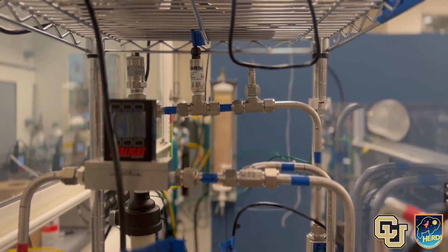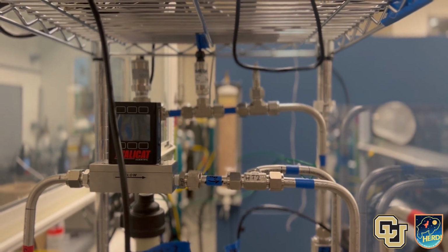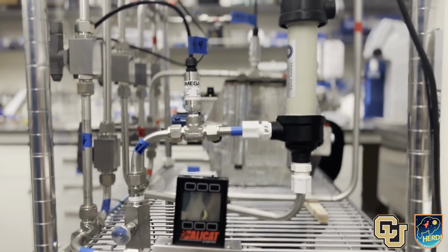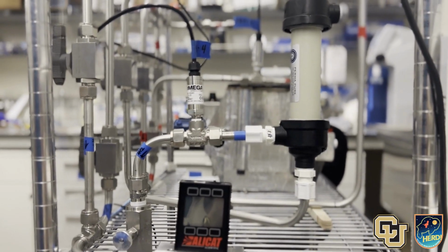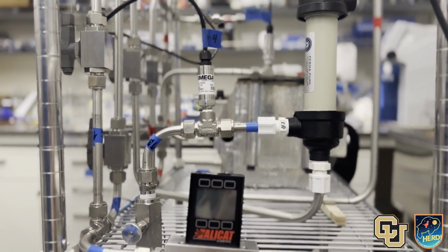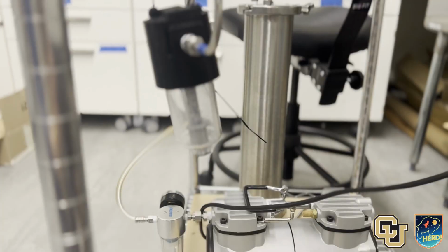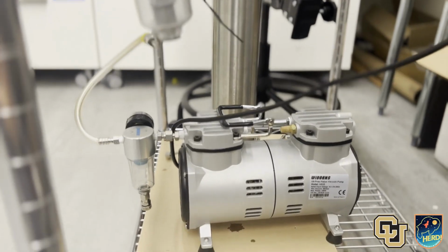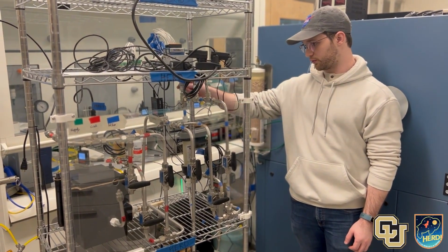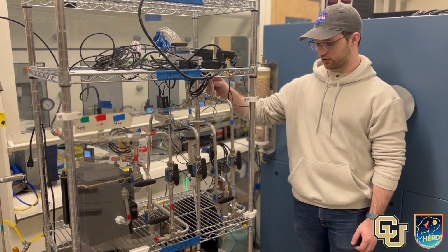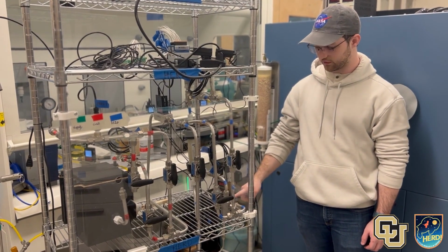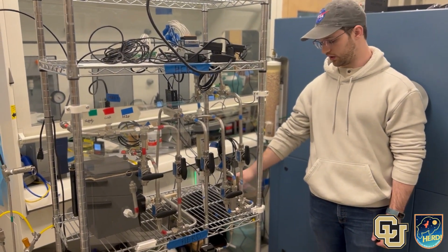And then that air is sent over to the humidity removal subsystem, which is a Nafion bundle, which removes the humidity through a difference in partial pressure of water vapor between the airstream and a vacuum line. And then the returned air that has no CO2 and hopefully just the correct amount of humidity has a dew point sensor, pressure sensor, temperature and relative humidity sensor, and then is vented through a flow meter into the atmosphere.